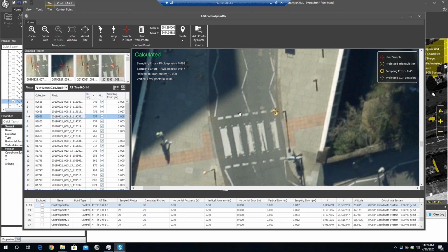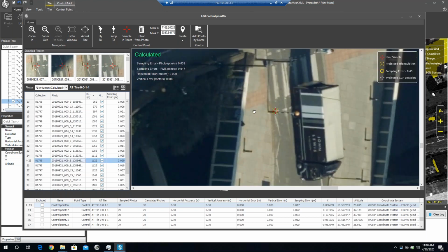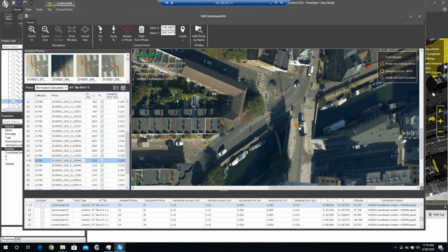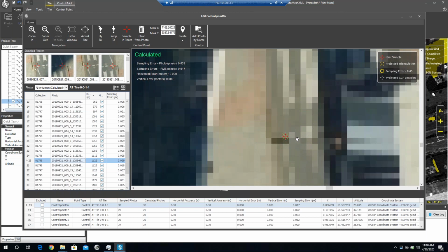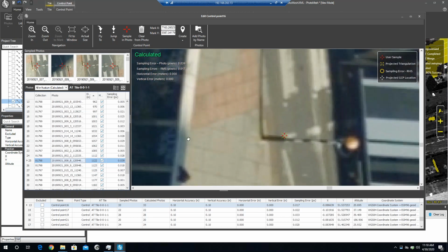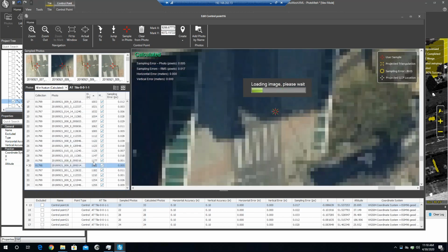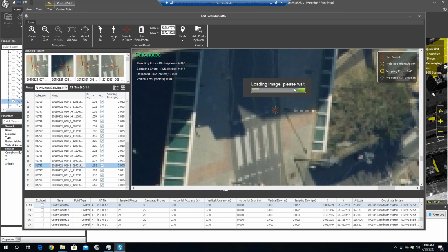This also helps align things to the LiDAR and helps the images overcome some of that when they go through the point cloud generation, the dense point cloud extraction. We can see this is an oblique image, as you can see, based on the view of the buildings from the side and viewing the building facades. And the same point gets referenced in also those images.